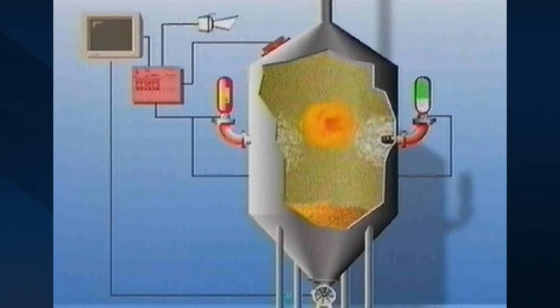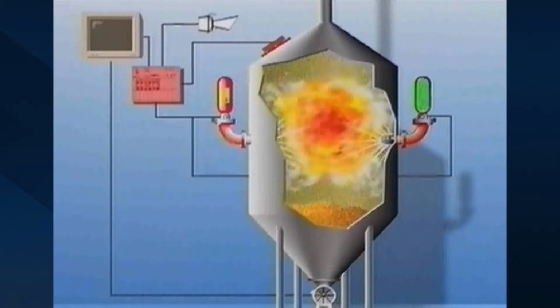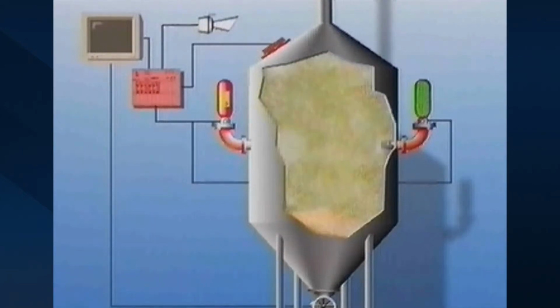The maximum pressure we always get when the flame meets the wall, that means when the reaction surface is biggest. Therefore, with explosion suppression, we can achieve quite low reduced explosion pressures.